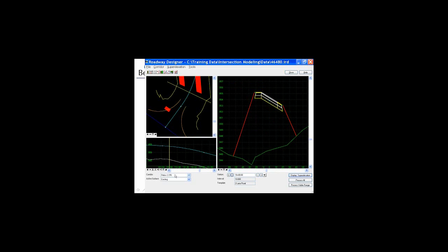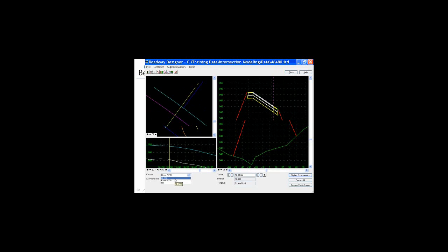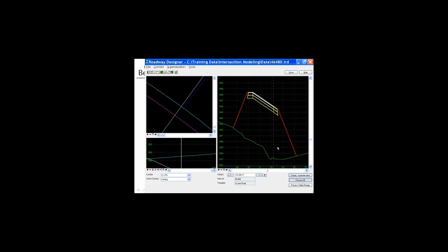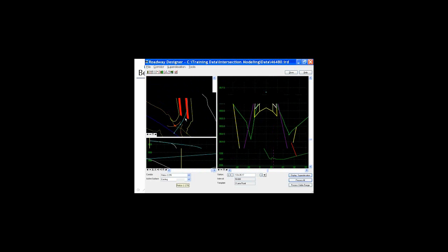If I go back to my centerline 278, reprocess that corridor, swap back to my relocation number 2, you will see that we wound up with a processing alias dialog. It was very quick, but what it is doing at this point is processing in memory a fictitious or a pseudo surface of the main line.